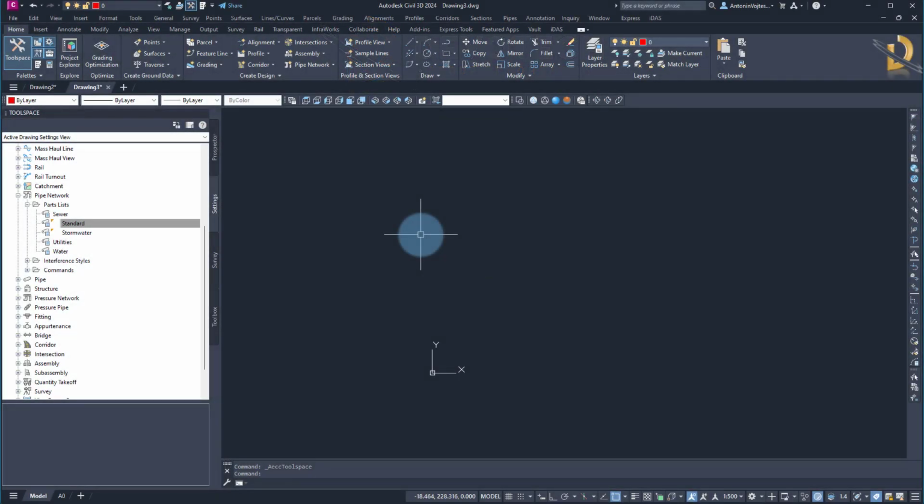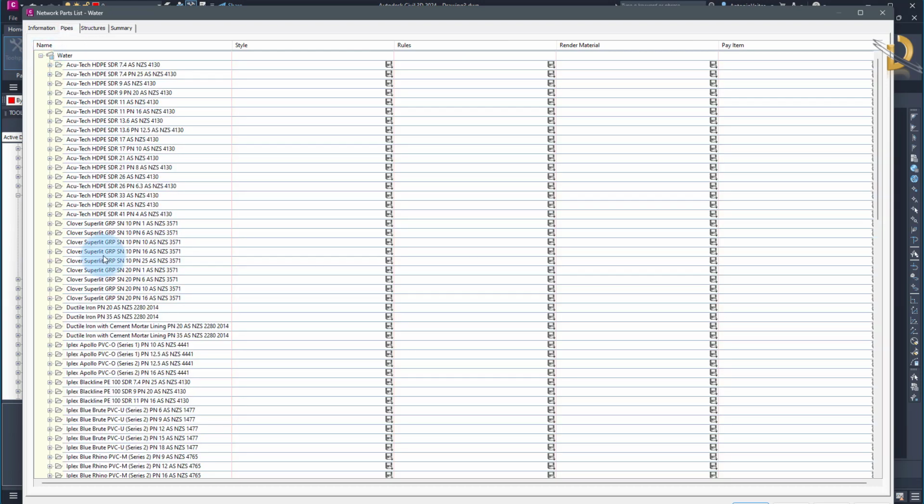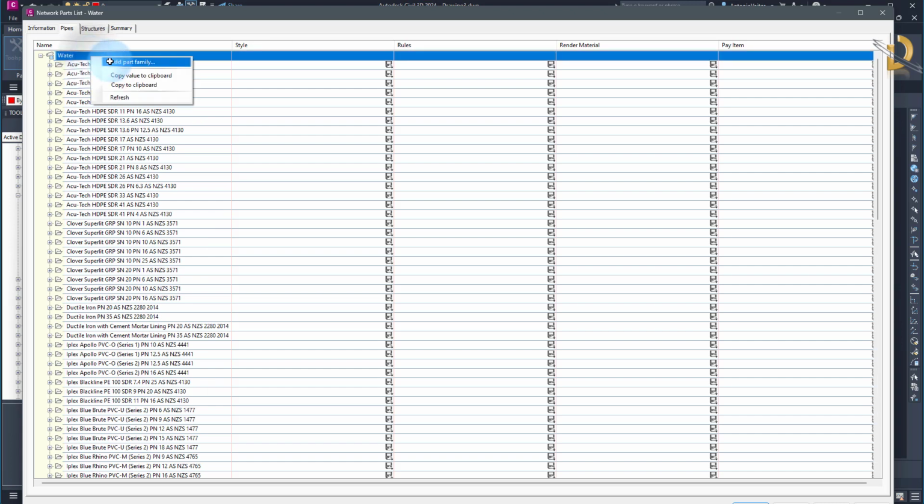In this video, I'll explain a little bit more about the pipe network catalog and part list. In the previous video, I showed you that we have a part list, and those part lists come from the pipe network catalog. If I right click, let's say on a water part list, and go to edit, then under the pipes there are a lot of pipes, as you can see. And if I want to import other pipes, I can go to add part family, and that opens a window where I can import a part family from.